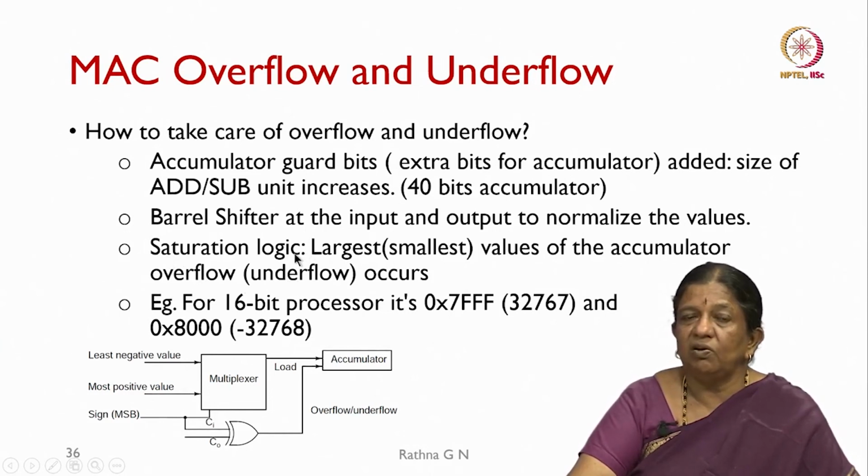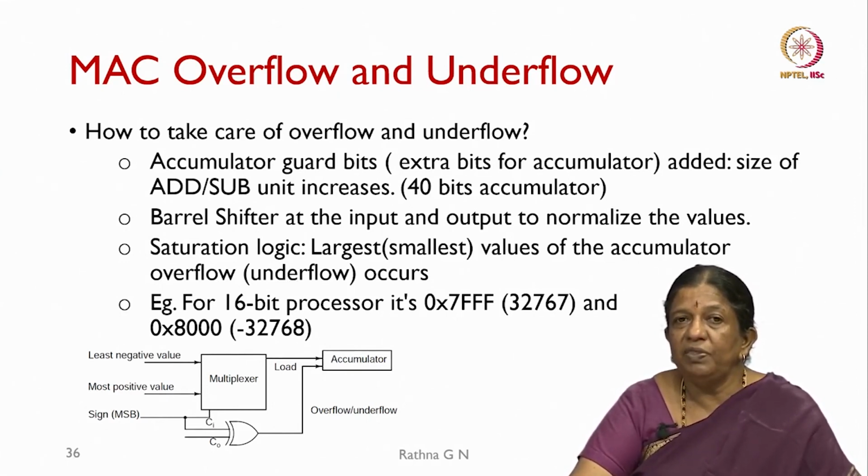the saturation logic. We know that when saturation happens, if the value is more than whatever the processor can represent, it goes to a negative value. So, we want to restrict it to the maximum value. So, the accumulator has to stop at the largest value on overflow.